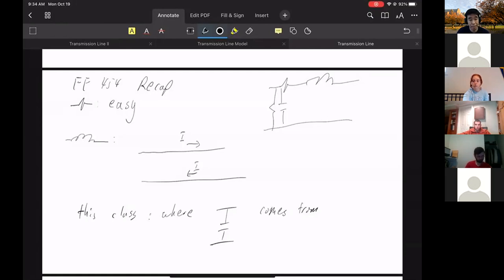Again, you'll see some integrals, but remember that all these integrals turn out to be easy. What we should remember is the dependence on different parameters. The exact equations you can look up, but we should remember, for example, when the distance between the conductors gets large, is the inductance larger or smaller? These are intuitive ideas we should have.